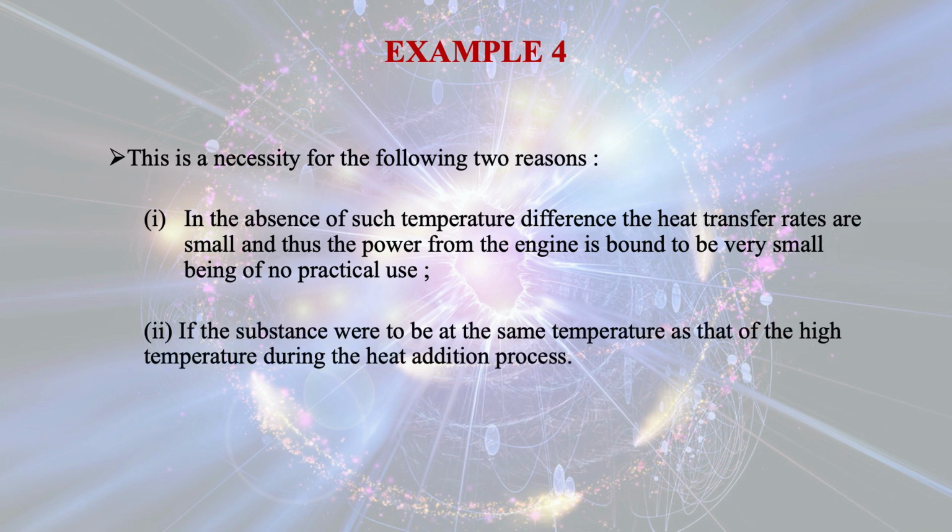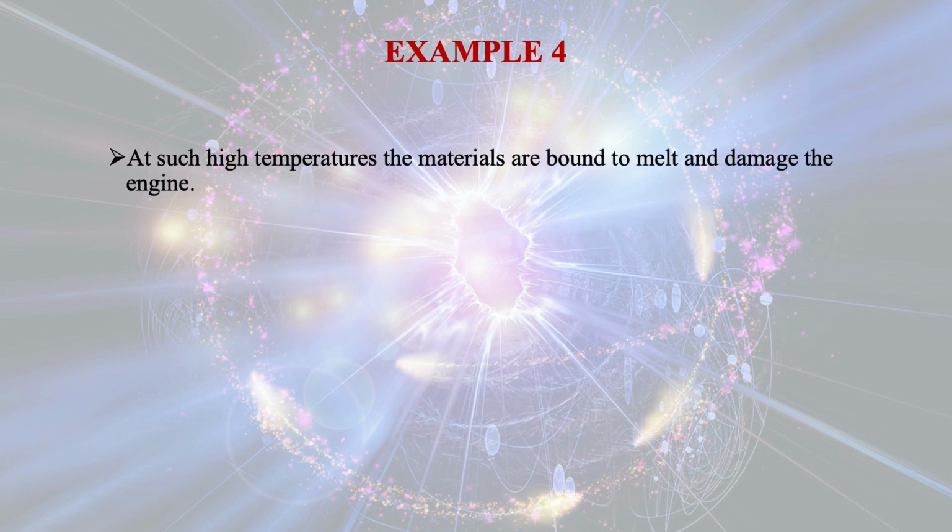Number two, if the substance were to be at the same temperature as that of the high temperature reservoir during the heat addition process, at such high temperatures the materials are bound to melt and damage the engine.